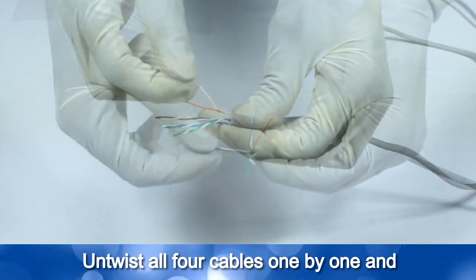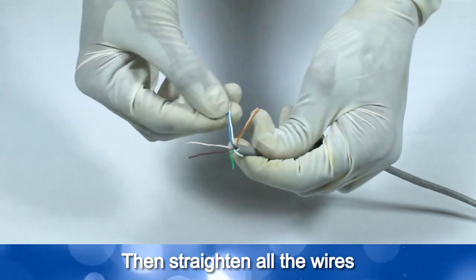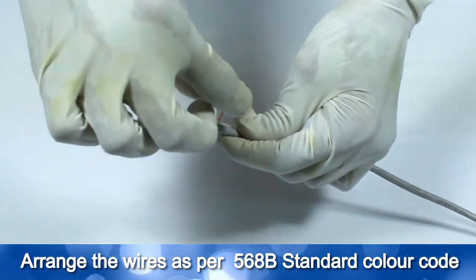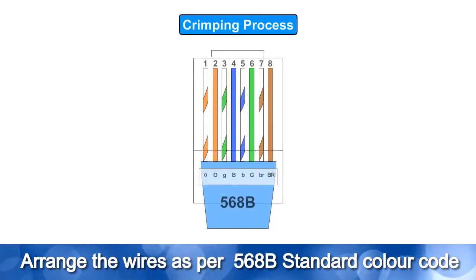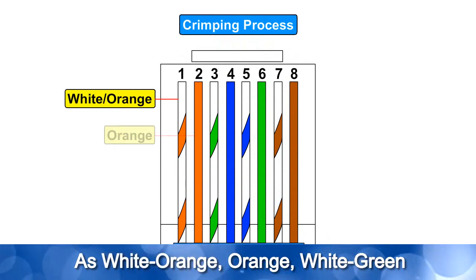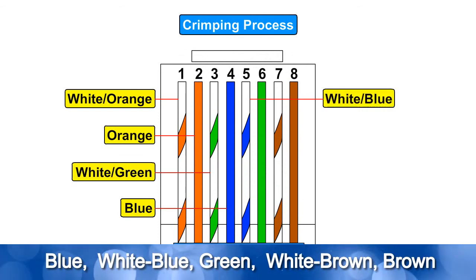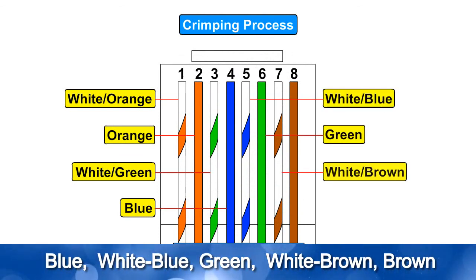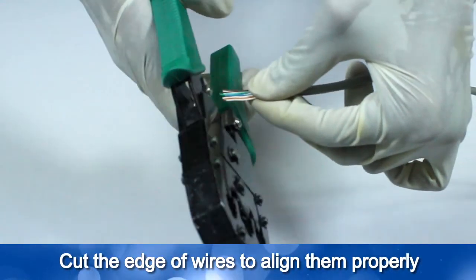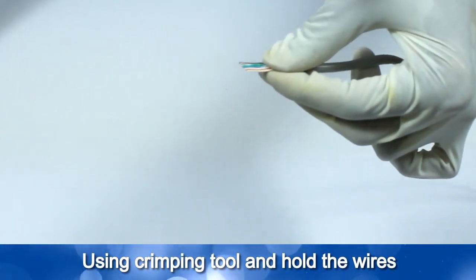Untwist all 4 pairs one by one and then straighten all the wires. Arrange the wires as per the 568B standard color code: white orange, orange, white green, blue, white blue, green, white brown, brown. Cut the edge of the wires to align them properly using the crimping tool and hold the wires.